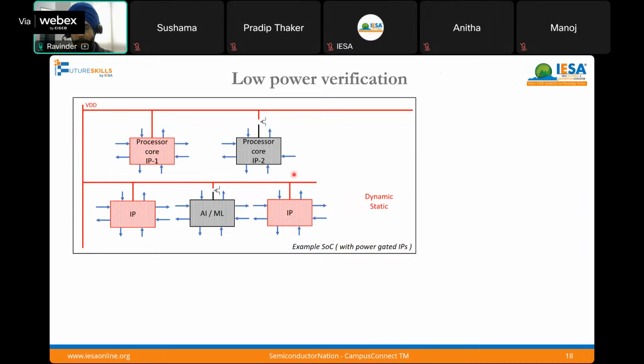So as a power saving technique, the power to unneeded IPs or unneeded features is gated off, and gating off is done using a PMOS switch. Once power is gated off completely, we eliminate both the dynamic as well as static power. So this is the motivation for doing power gating of some of the blocks, and this is in the low power architecture of the design.